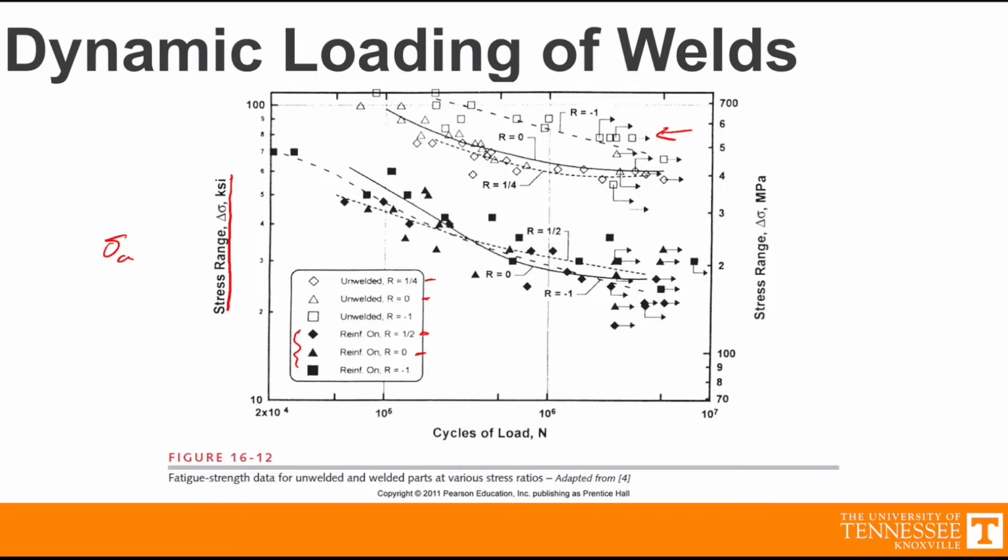It's polished, it's got a very high machining tolerance, but that's not necessarily the case for these welded parts. And actually, the tests that have been run on welded materials are close enough to the actual material that we weld with that we don't need to worry about correction factors when looking at especially surface finish, size, and that sort of thing. The testing results were close enough to what is nominally welded in machine shops around the world that we don't have to worry about adding these knockdowns to our fatigue strength.